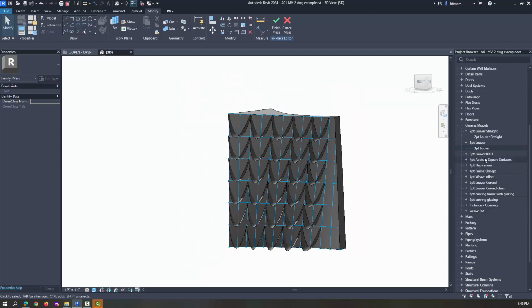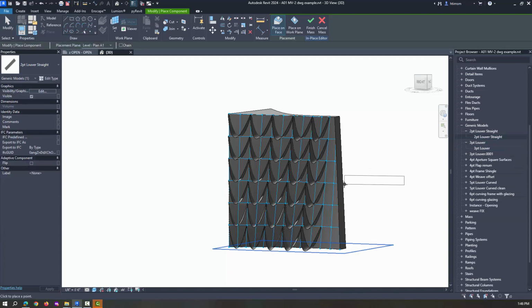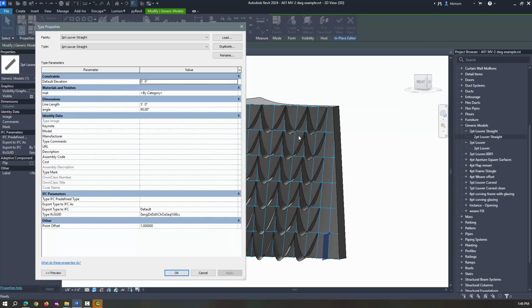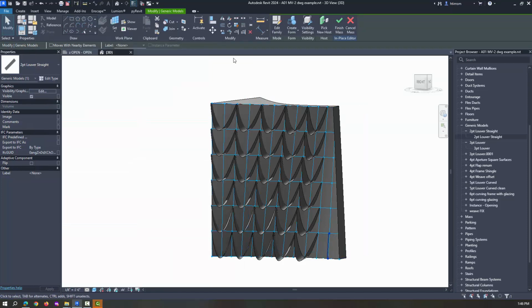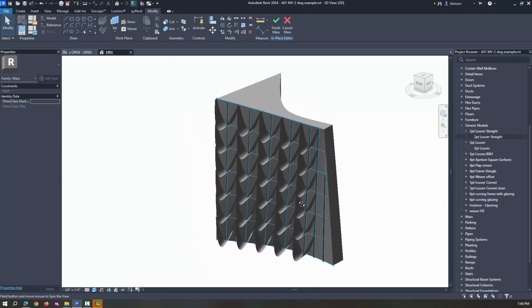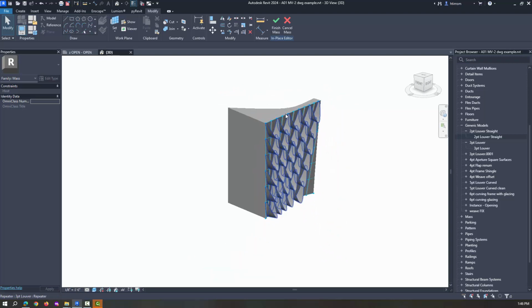Maybe I'm going to come in and drag the 2-point louver in, and I want some kind of verticals going through here as well. So I'll pick that guy and edit type, and let's pull it down to like 1 foot. And then I'll repeat that, right? So if I repeat that, now I've kind of got that guy rolling along with that.